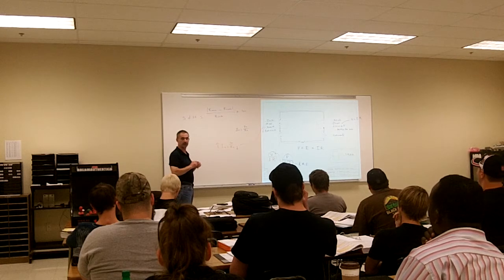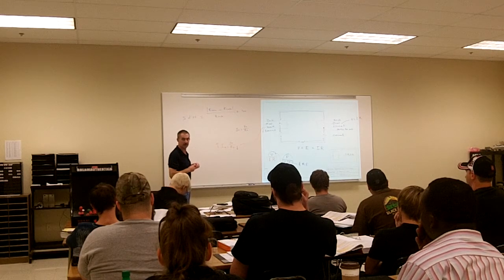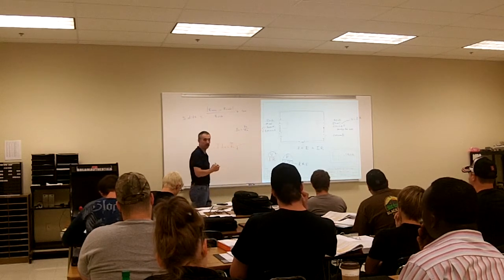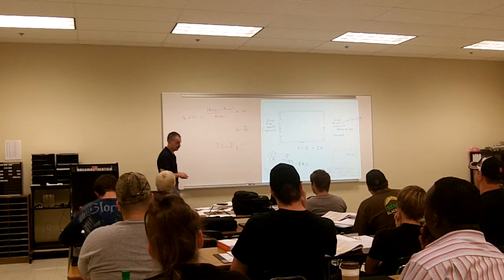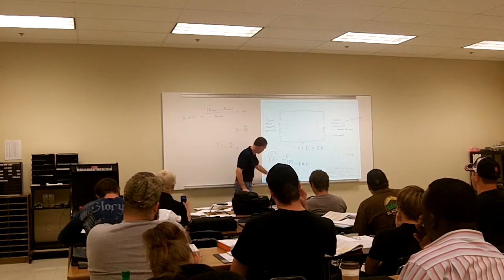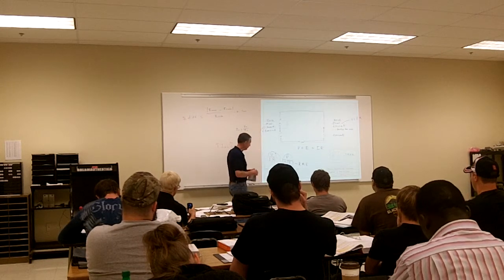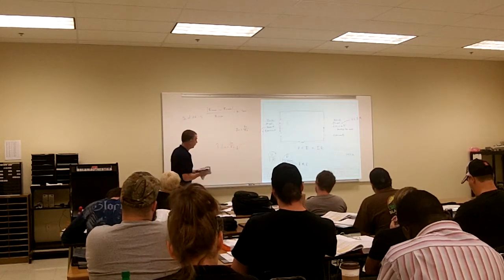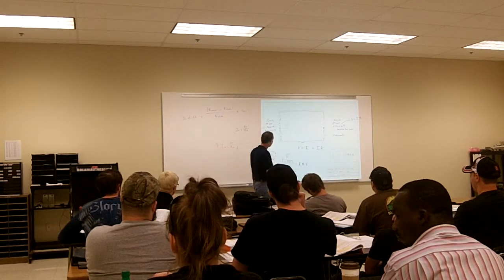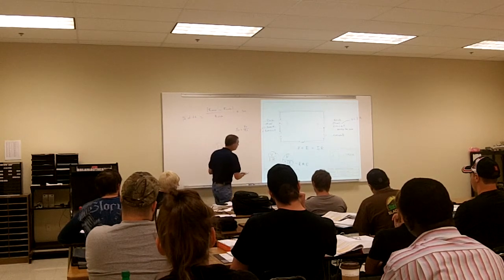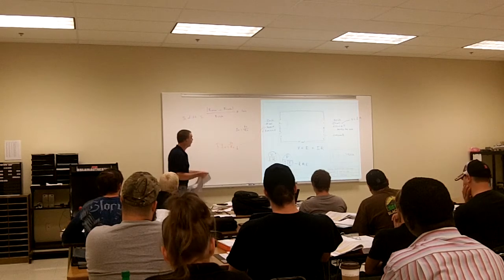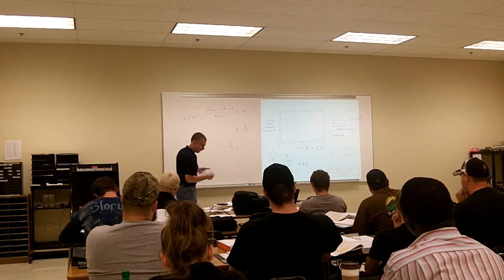And so what do we get for a percentage of difference? 1.25. Is that all it is? 1.25%? Then that would be more than acceptable, so we can go ahead and throw that into our circuit. Okay? We have to be careful because we have to meet these guidelines. We have to make sure that all resistors are within plus or minus 5% of our tolerance. So when you're typing in your resistors, make sure you double check it on your circuit there. All right. Any questions on that? Pretty straightforward? Okay, good.